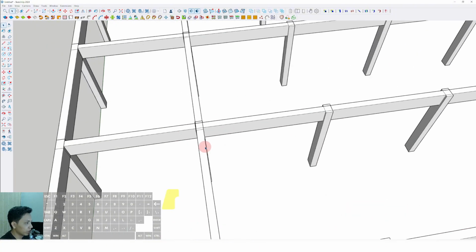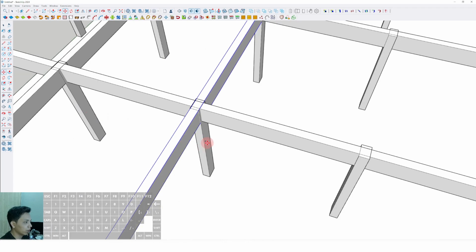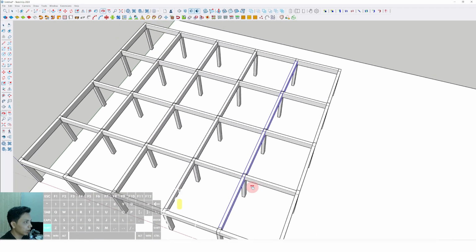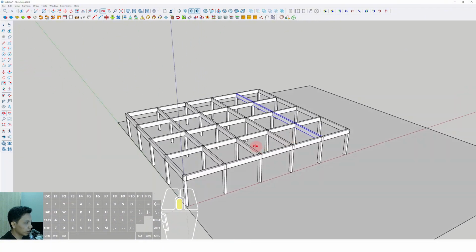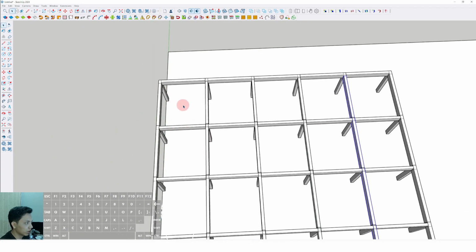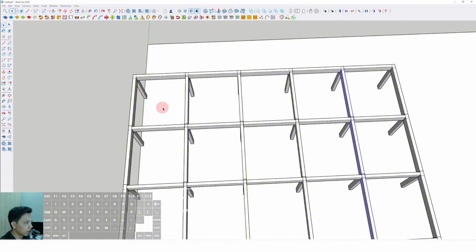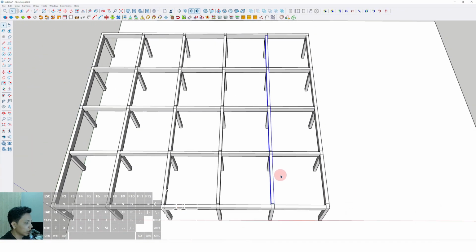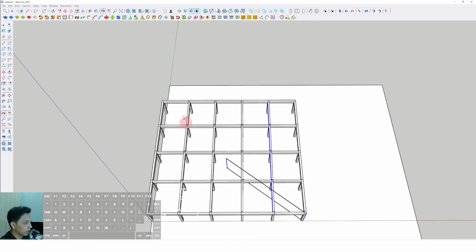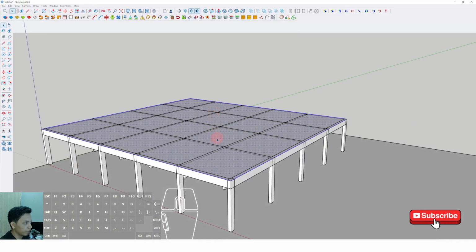We select Move and press Control and duplicate it again and again, making sure the whole path of the beam is fulfilled. For example, like this, we can decide that this is for the stair area: this is the surface stair area and this is the commercial stair area. So we select Rectangle and make a plane on this position.